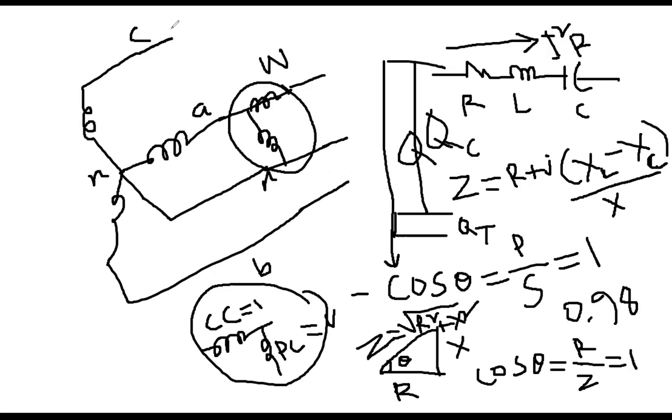always the system might not be exposed in that way. You might not always see that you are getting the neutral line. So if you don't have the neutral line, for example, it is just this type of box. You are not looking inside. Only you can see there are 3 leads, a 3-phase system, like A phase, B phase, C phase. Then how would you connect the wattmeter? Because this is A phase, B phase, C phase. You can't see the neutral and you don't know what's the internal construction.